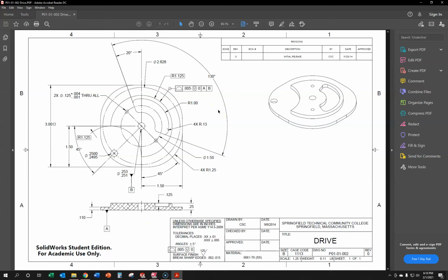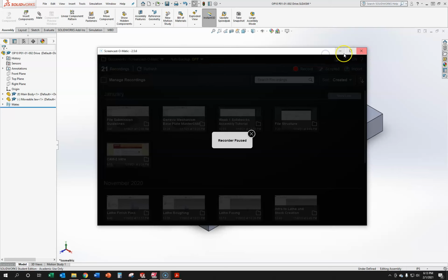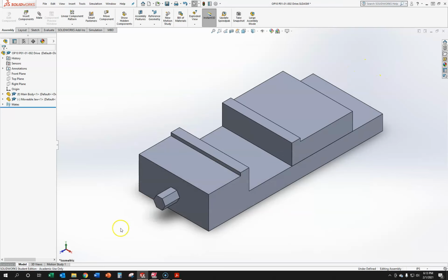and then we'll just machine the outside profile using 2D high speed. So we'll go 3¼ square, and then what we'll end up doing here is we will go ahead and make the thickness 1/2 inch or so, something like that. That way we have a 1/4 inch of stock to hold in the vise while we're doing our work holding. So let's go ahead and draw that piece of stock. That should be the first thing that we do.